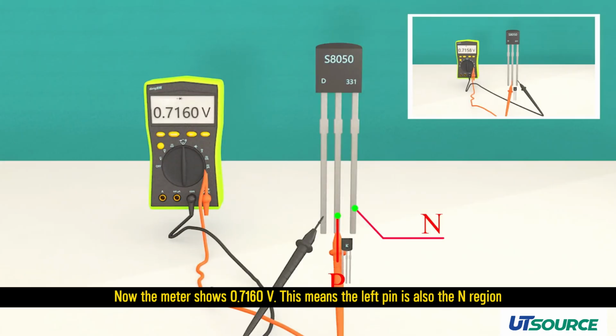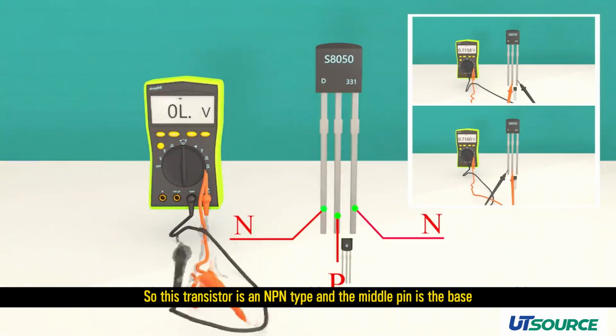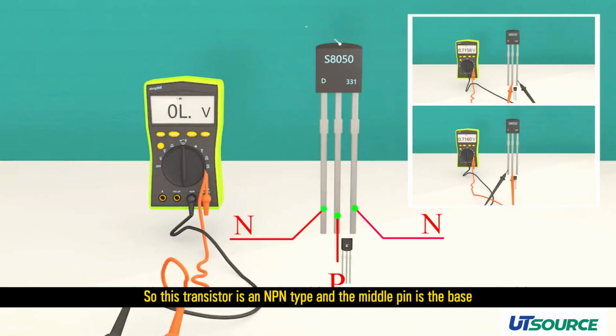Now the meter shows 0.716 volt. This means the left pin is also the N region. So this transistor is an NPN type and the middle pin is the base.